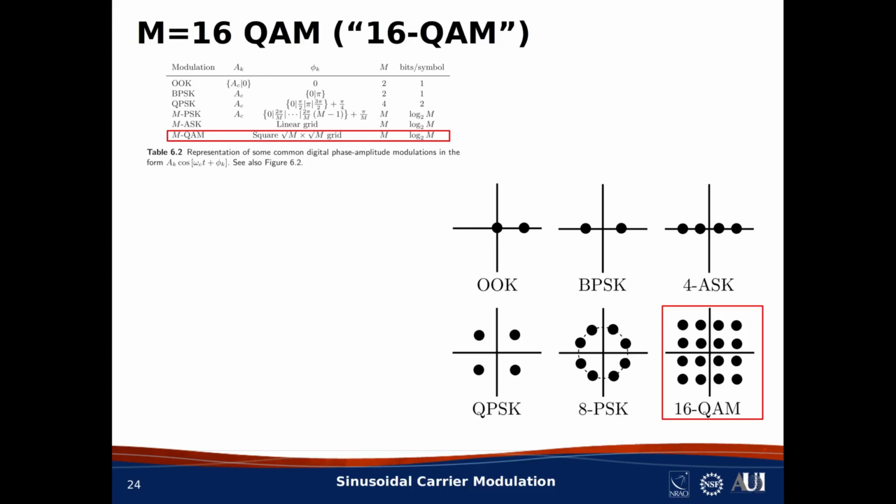That is, you can send 4 bits at a time. Now, how big can M ultimately be, you might ask? Well, the answer is as big as you want, but there's a trade-off. And that trade-off is that performance in low signal-noise ratio conditions typically gets worse as M gets larger. Nevertheless, it is not uncommon to see 256 QAM, 1024 QAM, and beyond.